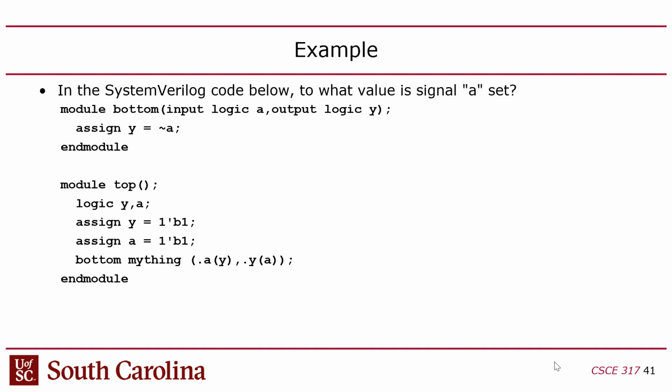It's going to be the worst case scenario because my thing is going to be trying to set A to 0. We know it is because the input is 1, so the output is 0. So this is going to be trying to set A to 0, and this assign is trying to set it to 1. So now not only do I have a double-driven signal, but it's actually double-driven in the bad way, where you got a disagreement there, right? So this will end up becoming X in the simulator, right? And if you did this in actual hardware, it would potentially damage the chip.